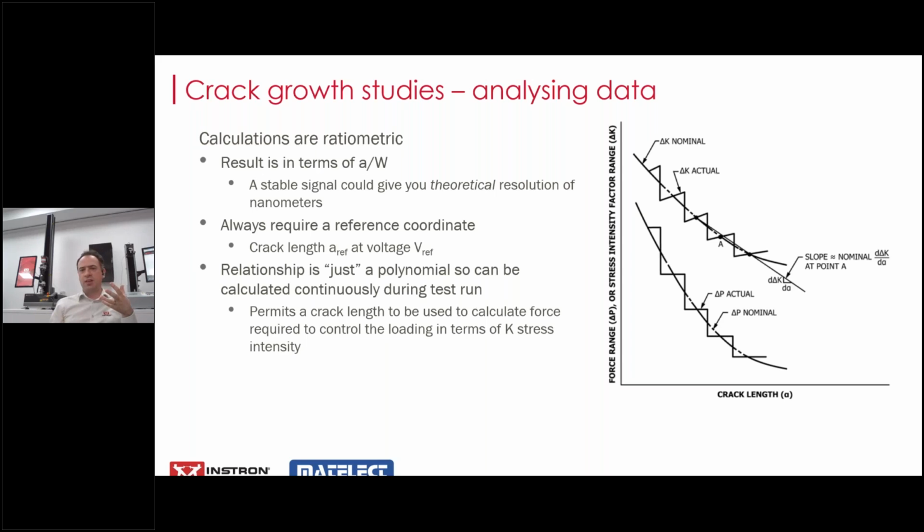I've borrowed this schematic graph from some of the crack growth standard test methods. You can see the force range or the stress intensity is on the vertical axis and the crack length is on the horizontal. If you're looking for a threshold stress intensity, the point at which the crack growth with cyclic loading becomes negligible, you want to gradually come down.